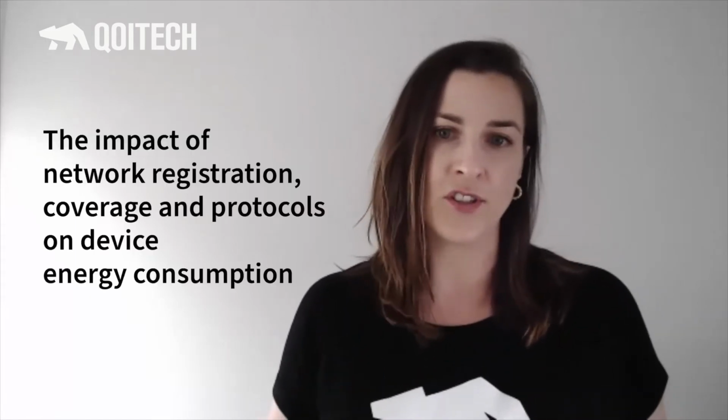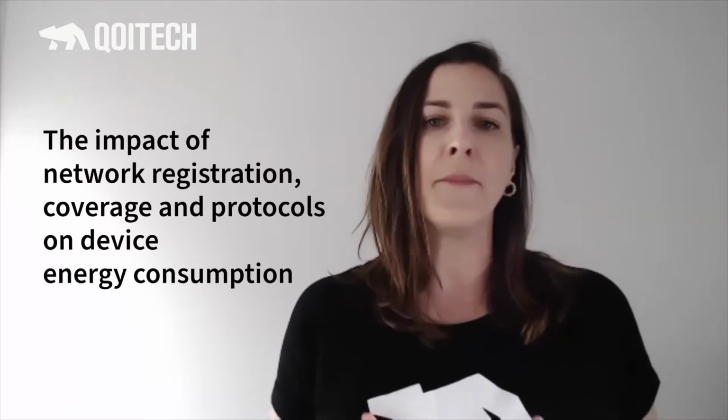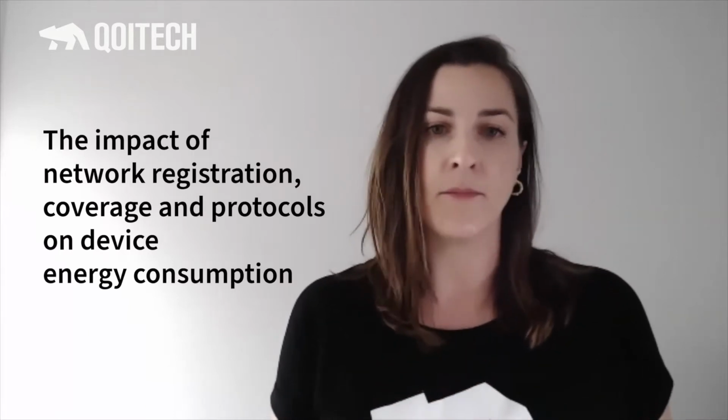We know that different operators have different settings, which means that a device may not be able to maximize, or in some cases not even use some of the low power features. How does the network registration work, and what impact can it have on the power consumption? Registration could be quite complex, and this of course is quite important for your power consumption. There are so many frequency bands available that the scanning of all bands can take some time.